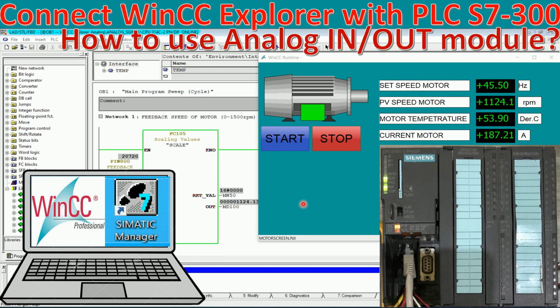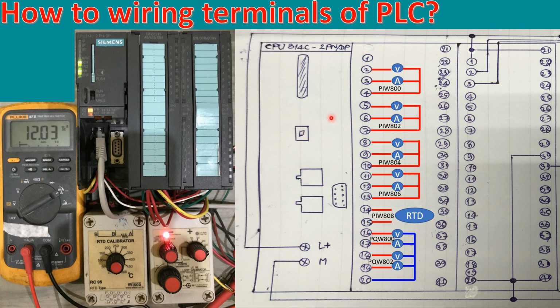One more very important topic is how to wire the terminals of this module. All these terminals are connected with the analog signal. The default address starts from PIW 800 and ends at PIW 809.